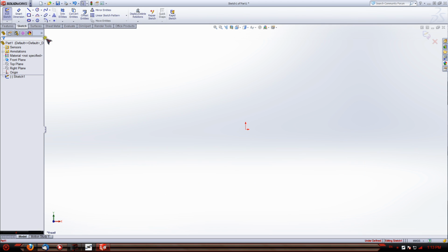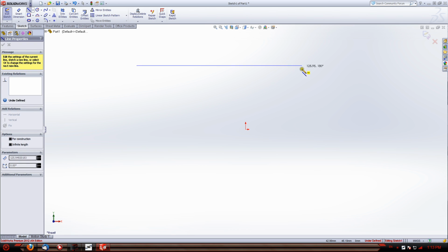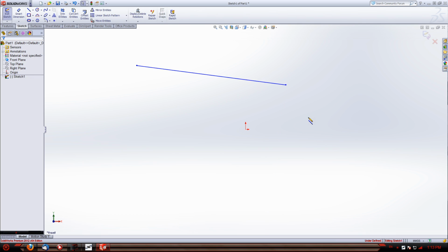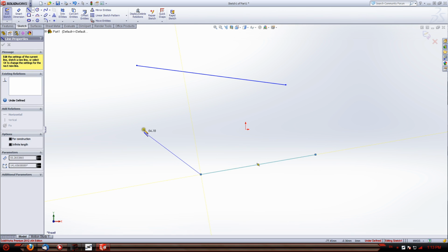All of your drawing tools are up here. If you watched the video before, I went through all of them and just kind of told you what they did, but now I'm actually going to use them so you can see what they do. We'll start with the line command. Obviously, click one point, drag anywhere else on the screen, and it'll create a line. Hit escape to end your command, and then you can hit enter if you want to continue, if you want to start a new line somewhere else, and then just hit escape again.